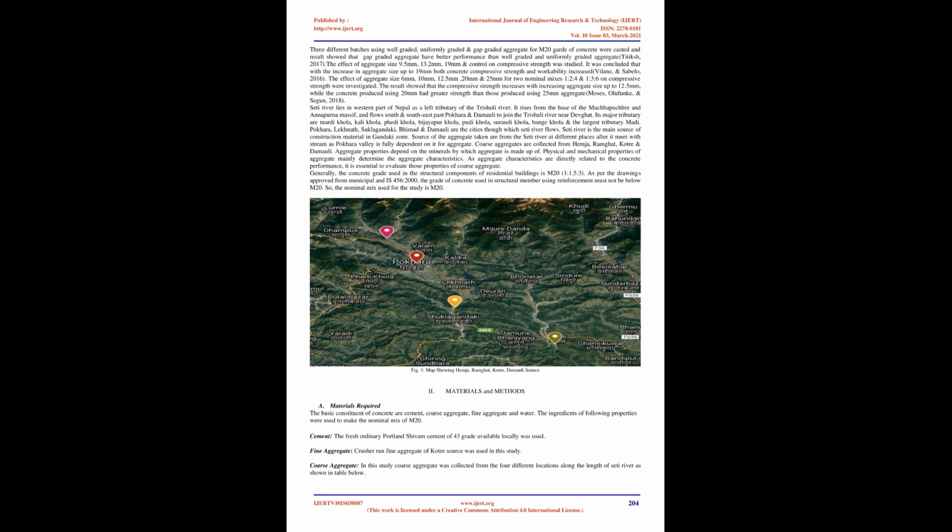Coarse aggregate of size 10 mm, 14 mm, 20 mm, and a combined size of these 3 based on percentage proportion were used for the preparation of concrete cubes, keeping W/C ratio, cement, and sand constant. In combined size aggregate the percentage proportion of 20 mm aggregate was constant, i.e. 50%, but that of 10 mm and 14 mm size aggregate were varied. The result showed that the combined coarse aggregate which contained 30% 10 mm, 20% 14 mm, and 50% 20 mm had the highest compressive strength.